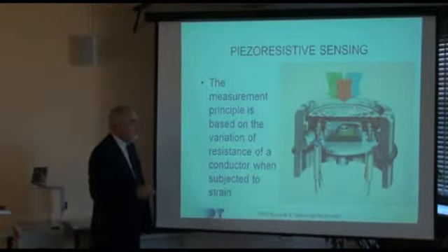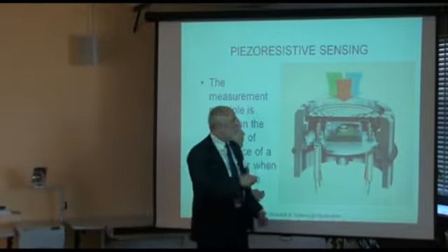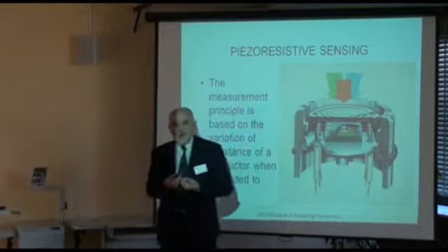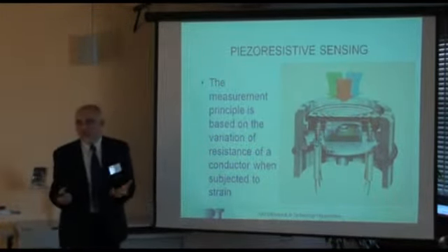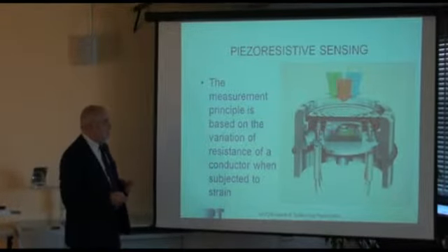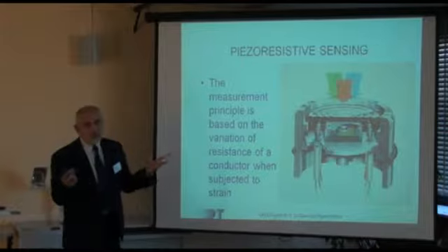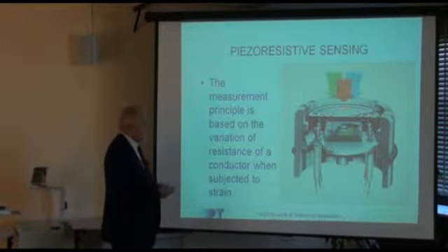And what we have in here is just a protective membrane to make sure that particles don't hit this membrane that is extremely sensitive. We talk about a few microns, 2-3 microns in thickness. We talk about 200-300 microns in diameter. It's very sensitive. Any dust or something could break the membrane, so that's why it's necessary to seal it.